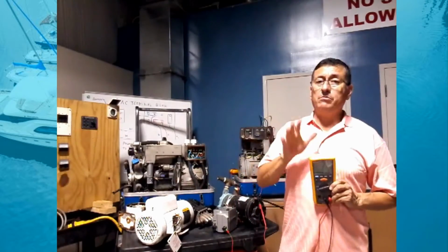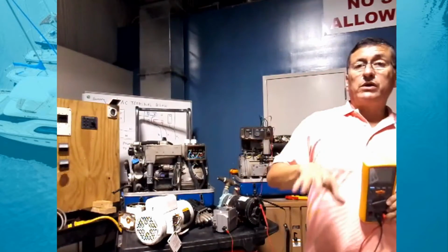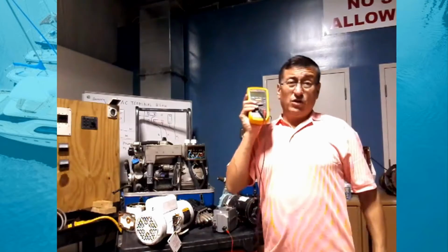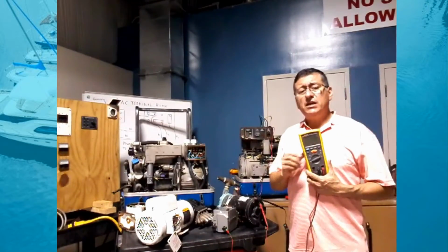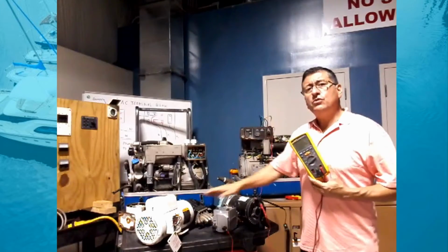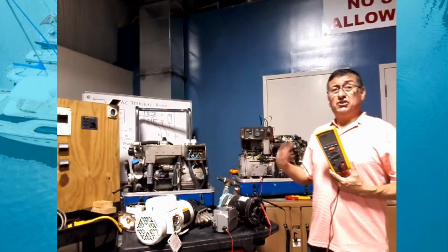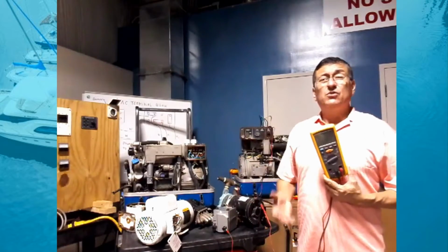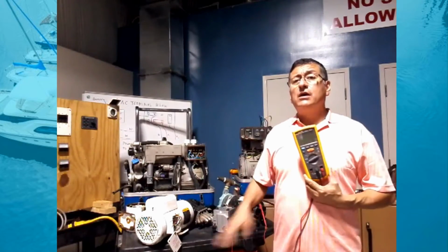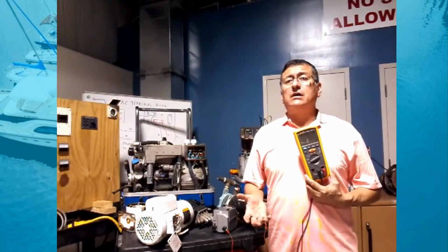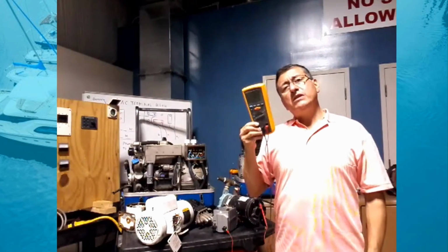You need the megohmmeter if you are working with marine generators, if you are working with marine electricity. Not only to check the back end of the generators. With the megohmmeter, you can check any motor, three-phase motor, single-phase motor. You can check the winding of alternators. You can check any winding. The alternator, the starter motor, the bow thrusters, any motor, AC or DC, can be checked with the megohmmeter.